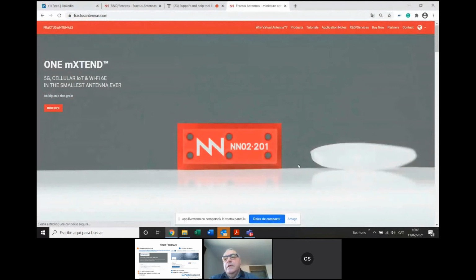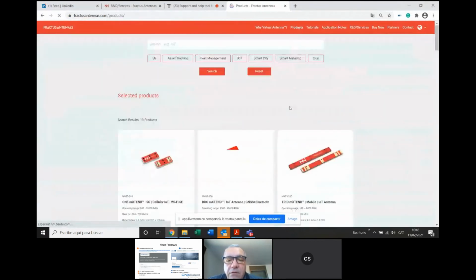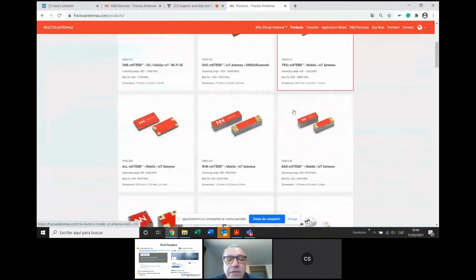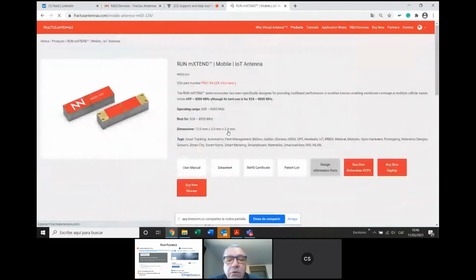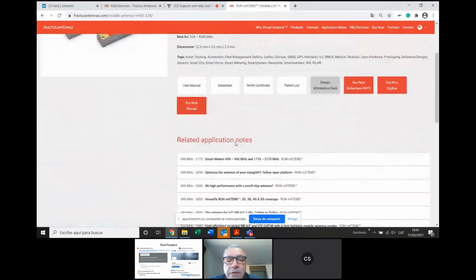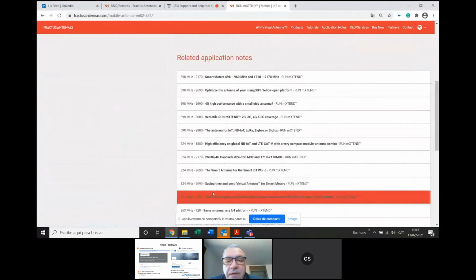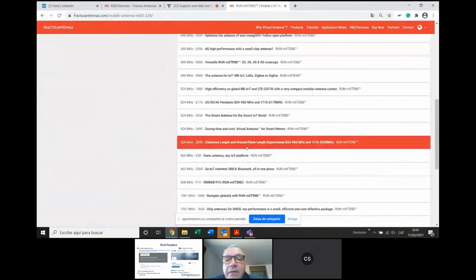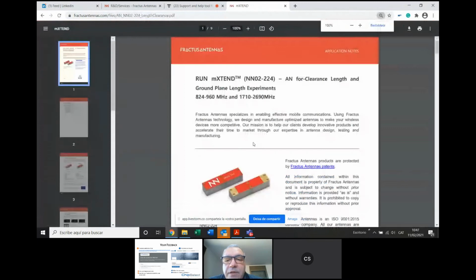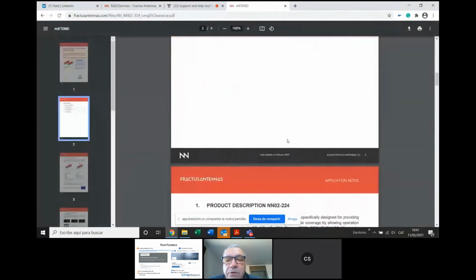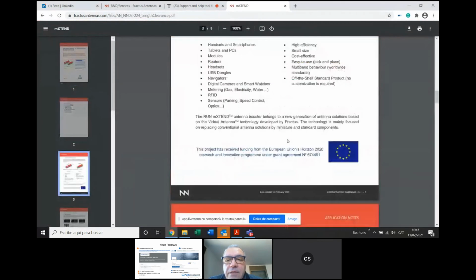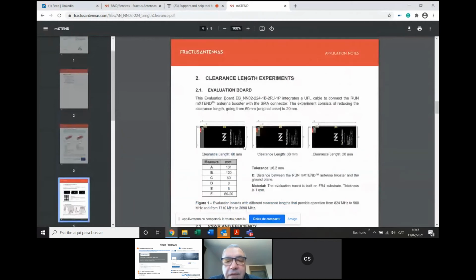Do you see my screen? Yes, we do. Okay. So we have many application notes, but if you go to products, one of our most popular antennas is this one, the 224. You go here, then you scroll down. There is one application note about experiments in clearance length and ground plane. You click on this application note, and it gives you the influence of the clearance area if we fix the PCB area and change the clearance area.